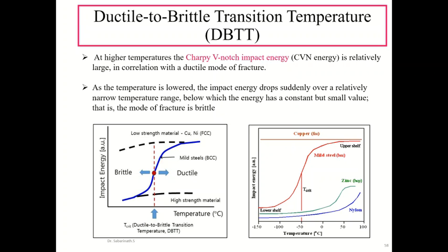But at a relatively low ambient temperature, a crack would be initiated at some point of stress concentration, and this crack would propagate, causing the failure of the material, and continue until it broke the ship. So this is due to the transition of the material from ductile to brittle fracture mode.